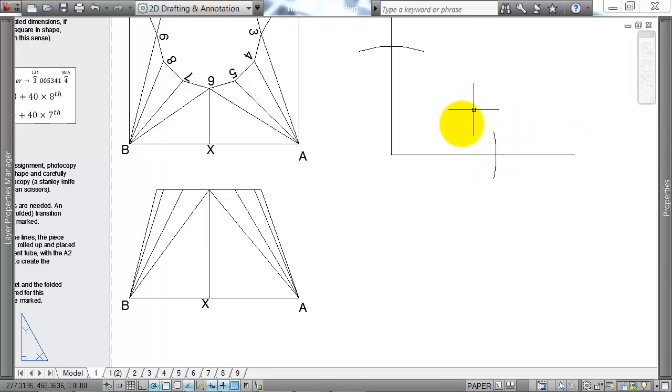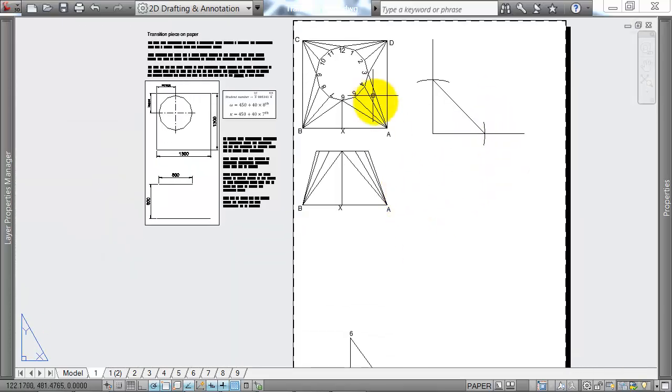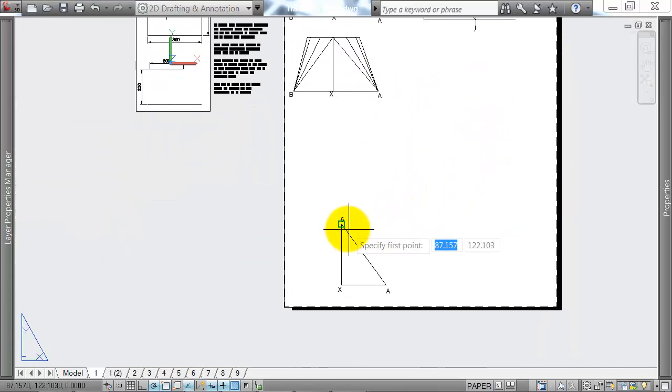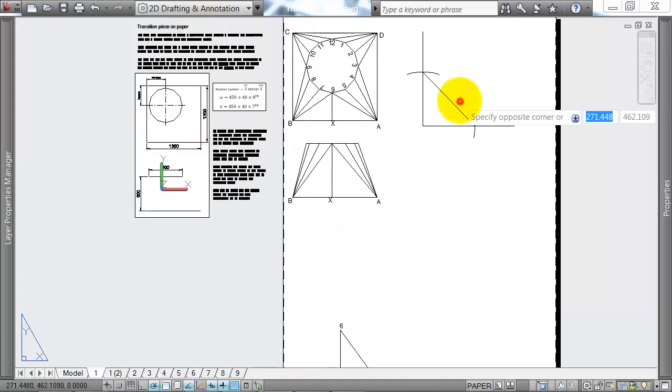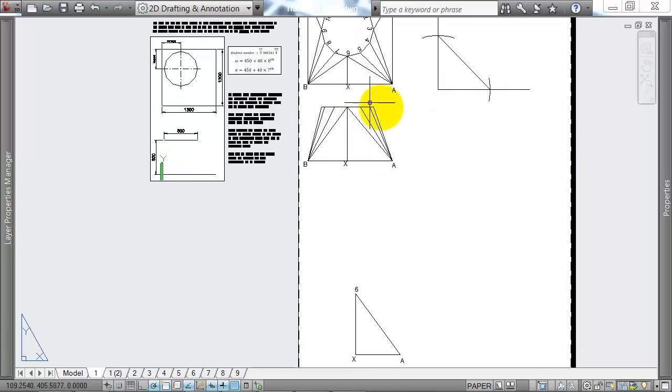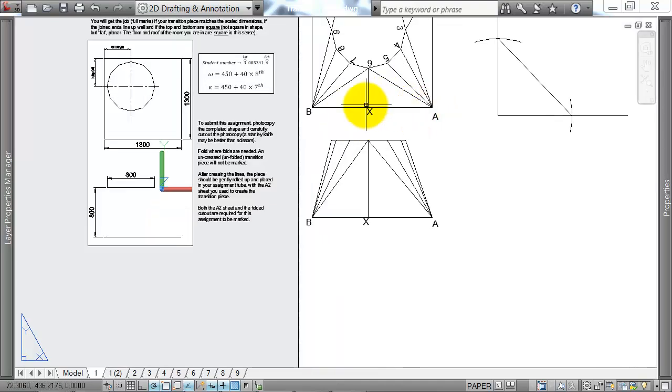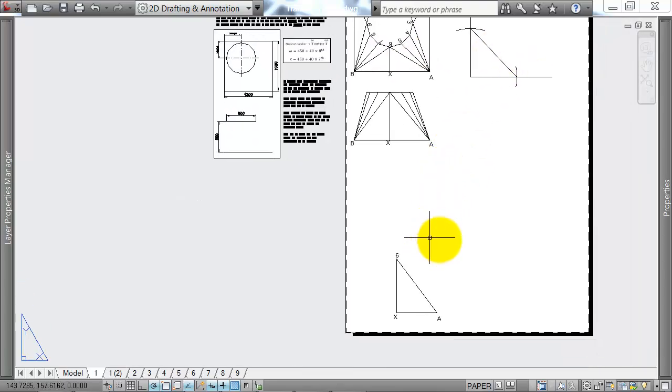Okay, so they're my two compass marks. Made a mark here with the compass, made a mark here with the compass. This should be the true length of line A6. 113.32, and I've got it over here as 113.32. So that's the correct method of doing this. I'm slowly building up the shape, counting the x direction, the y direction, and the z direction, not counting any of them twice.